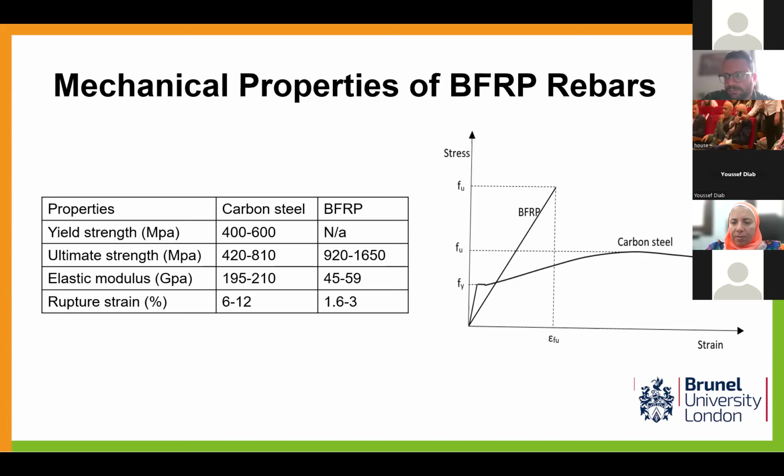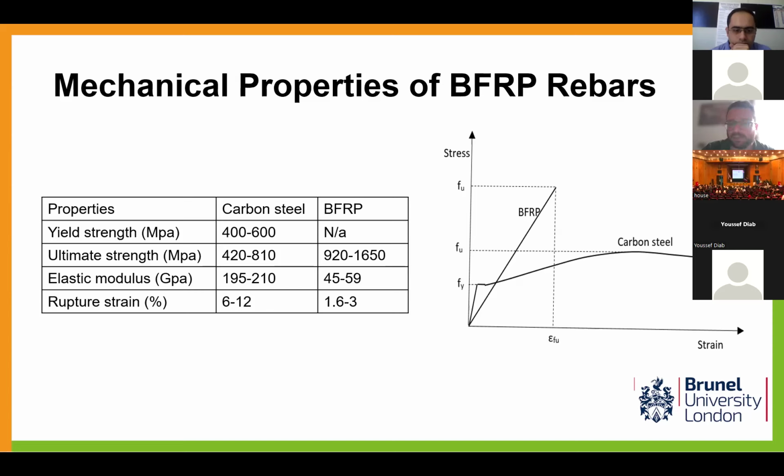Okay. Any other question? Just to mention, there's a misconception: okay, there's no ductility, so there's no warning before failure. But with BFRP, we allow a bigger crack width of 0.5 millimeter, which is fine for a few infrastructure types, but still we have to limit the crack width to 0.2 to 0.3. So there's a relaxation of the crack width for basalt, so it can be used even in an aggressive environment because it cannot corrode.